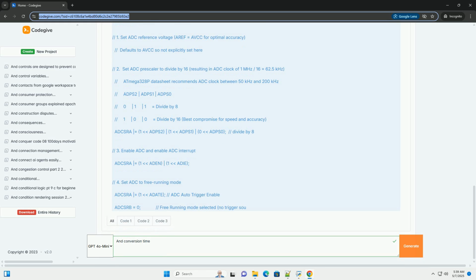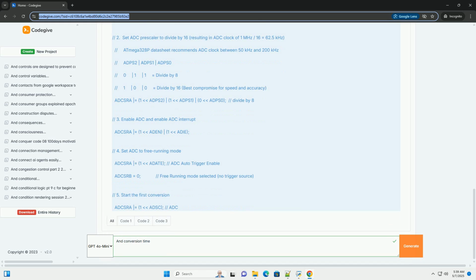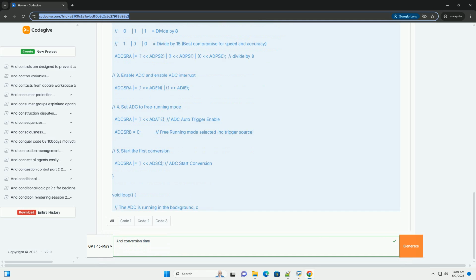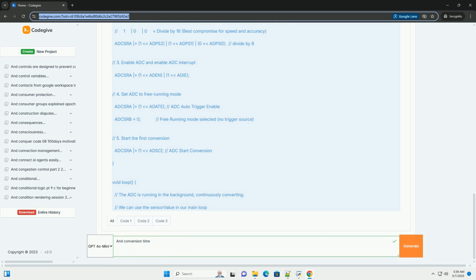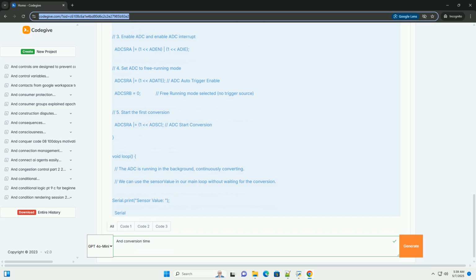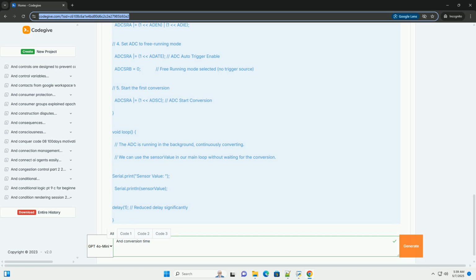This tutorial will provide a comprehensive overview of ADC conversion time, its impact on your application, and strategies for optimizing it. 1. Why ADC conversion time matters. Sampling rate and Nyquist theorem: the conversion time directly affects the maximum achievable sampling rate.